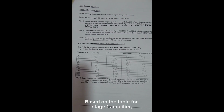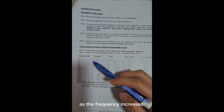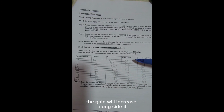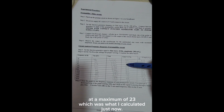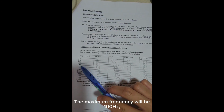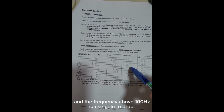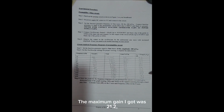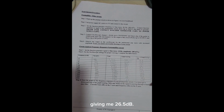Based on the table for stage 1's amplifier, as the frequency increases, the gain will increase alongside it at a maximum of 23, which was what I calculated just now. The maximum frequency will be 100 Hz, and the frequency above 100 Hz will cause the gain to drop. The maximum gain I got was 21.2, giving me 26.5 decibels.